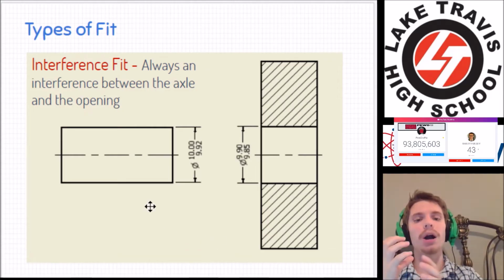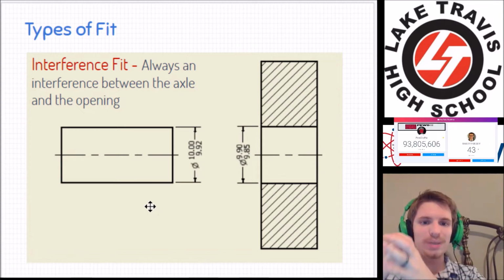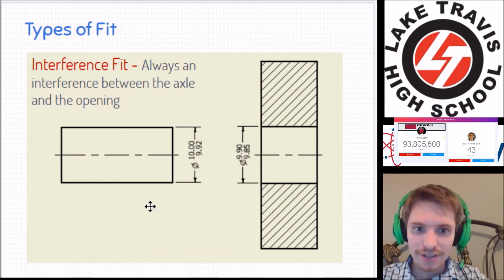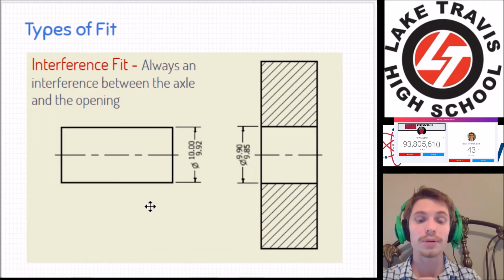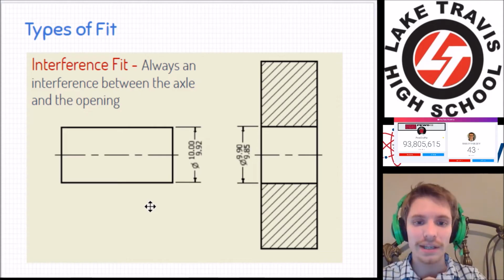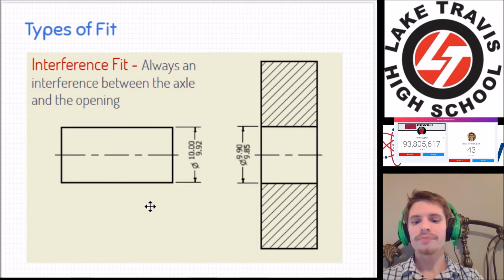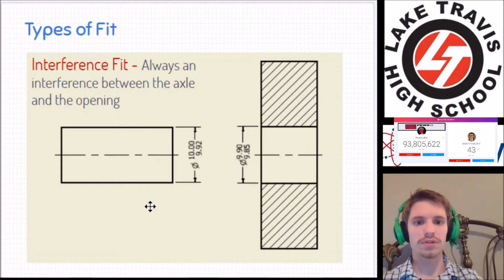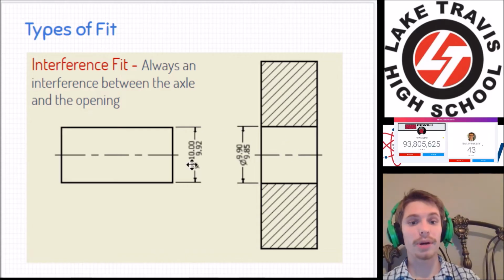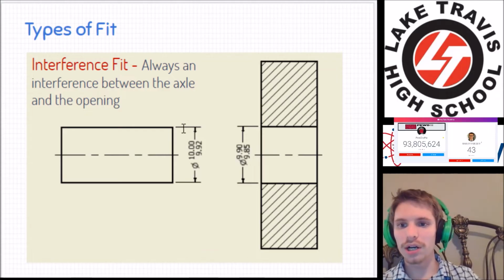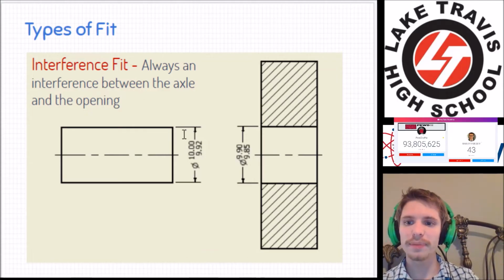What would happen is your parts would actually squeeze together. You actually compress those parts, especially with plastic. Plastic is more pliable or more compressible or more compliant. Compliant is a good mech engineering term. Compliant, so that it will squeeze into the opening here and it'll stay stuck in there. That's how parts actually work. They change dimension as you shove them in somewhere. So there is always interference, even if we make this as small.